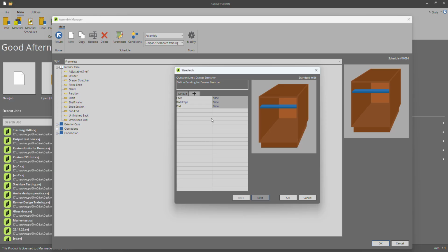It will be an overlay or underlay. No, it's actually basically what it does. Good question that you asked. You know the big carcasses you're busy making? Sometimes the carcasses go upwards. The stretcher pulls it back in. So you've got multiple drawers, and it also defines that look because you can bring the drawer fronts inset as well. Is there a stretcher there underneath that? Yes, in this cabinet where you have the stretcher, that's a stretcher. That prevents the carcass from blowing out. Otherwise, you see the little shelf in it. Yeah, that's a stretcher.